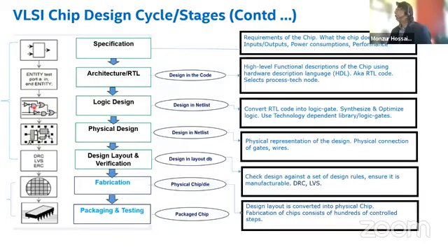There is an industry tool that converts it. The electronic design automation industry has a tool to convert this RTL code into gates. Synopsys, Cadence, Mentor Graphics, many other companies in the industry develop those tools, and the chip design companies buy those tools, or the universities use those tools, to convert your RTL code into logic level. And in this level, you also decide which process technology node you want to use for your chip. Is it 10 nanometer or 90 nanometer? So logic designer, in this stage, you pick your technology node.